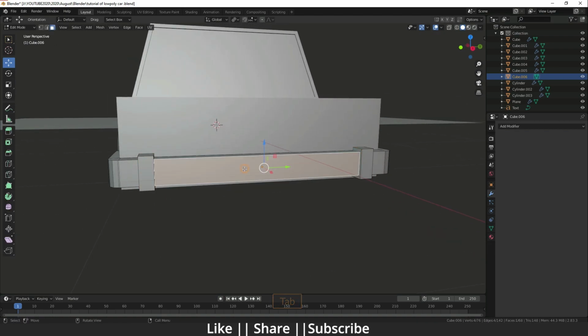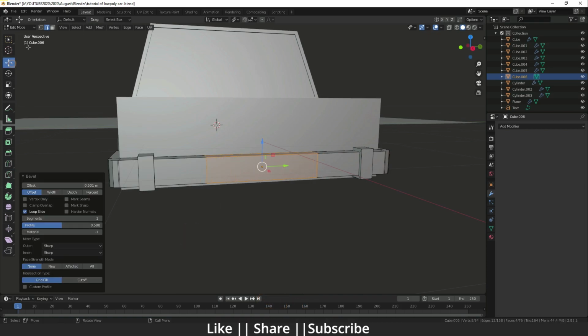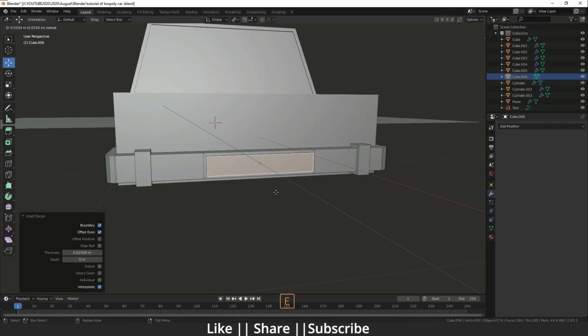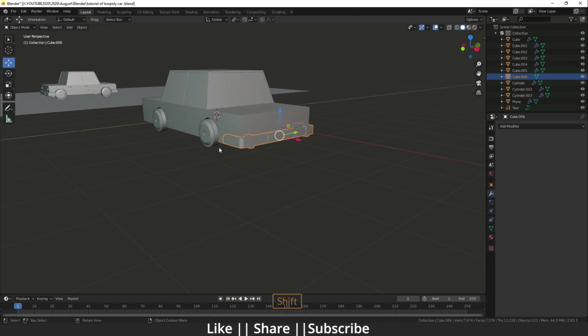Okay, then we will make a number plate. So for that I'm just going to add one edge loop like that, select that face and go to insert, and extrude a little bit like that. So we have a number plate also.